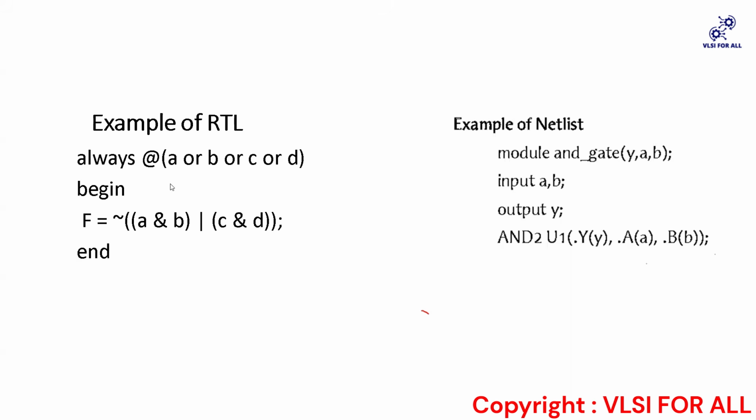Of course, we can represent it in the RTL also, we can do gate level modeling as well. You can say that it is the same, but here it is the optimized version. After synthesis, we get a netlist, right? It is the optimized netlist. And of course, both are represented in .v format only.